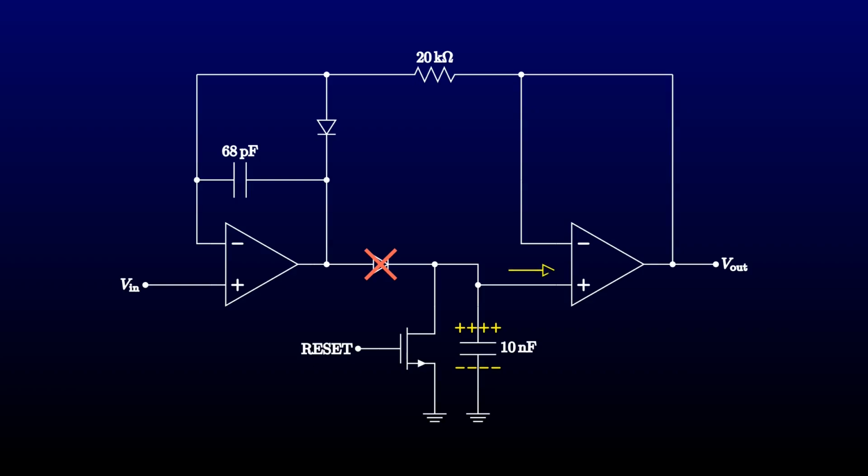Next, let's look at the op-amp input. The current flowing into an op-amp's input is tiny enough that we've been ignoring it up to now, but sometimes it's too big to ignore. The key datasheet parameter you need to look for if you need to control leakage through this path is called the input bias current.